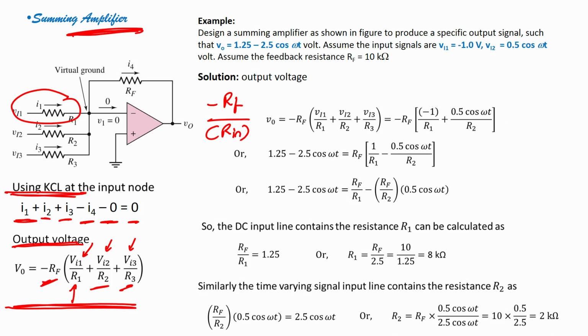That is why we say this is a summing amplifier, right. Now, here you can see very easily that the concept of virtual ground will come here. Because the non-inverting terminal is grounded, the voltage at the inverting terminal is also considered as 0, which is your virtual ground.